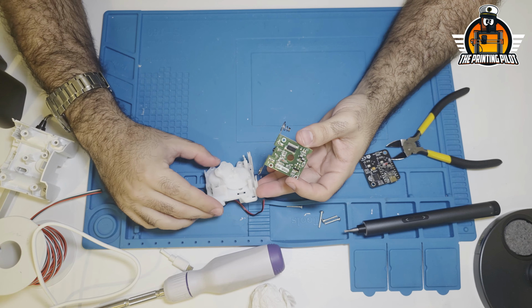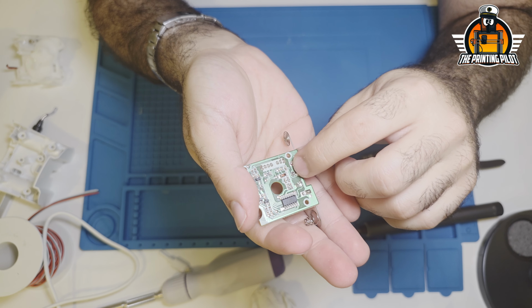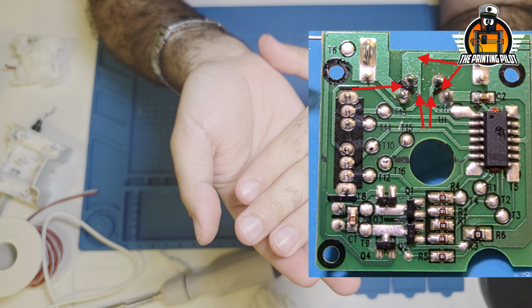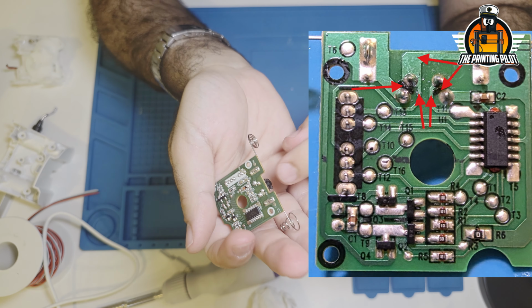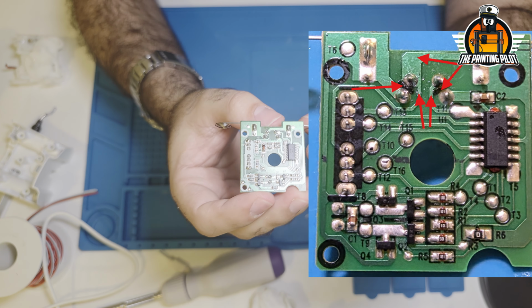And now I'm going to show you something. I'm going to put a bigger picture on the screen. And I'm going to show you guys that this button, this PCB, needs to be modified a little bit, because something is going on there and I have no idea. I haven't really looked into it too much. But if you don't cut those traces and modify it, this PCB will always send an on signal to our smart PCB we just built.